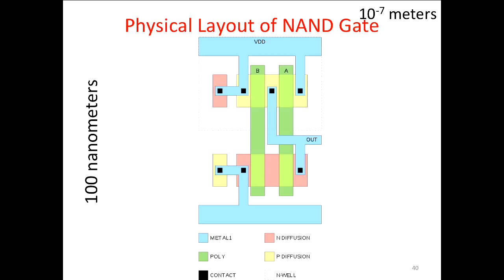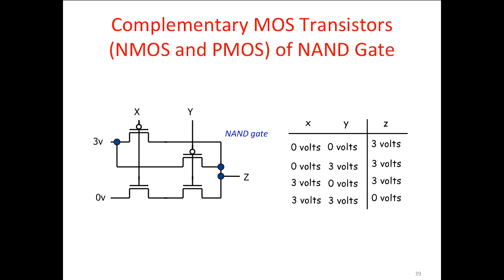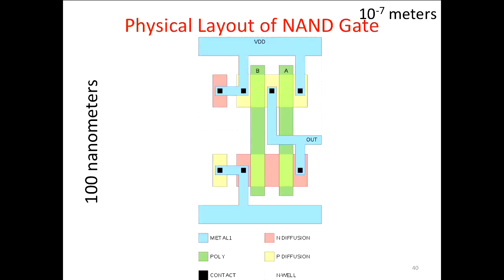And they do other kinds of tricks to reduce the capacitances, like this trick about this node, which is here, between these 2 transistors. They actually share that between these 2 guys to reduce the capacitance on this output node, right, to save power. So there's a lot of details in this physical design. There's expert designers who spend their lives looking at screens and packing this stuff very tightly.